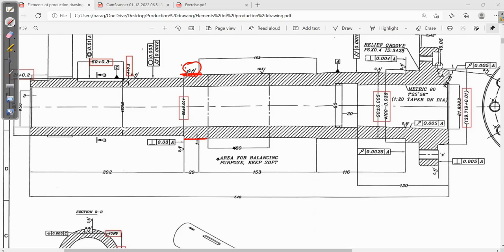So in this case it is 0.4. Again, if you see, next thing 0.4. Here the bearing surface touches, so 0.4. As per our application we have to keep that surface roughness. Suppose we purposely keep it rough, 50 microns we can keep. Suppose we need it smooth, as smooth as possible, 0.2, 0.4.